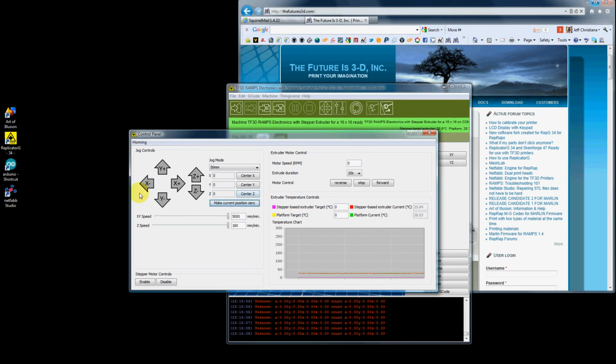These numbers mean nothing when you start printing. This is only a way of manually moving your bed and print head around. This is only for testing. It doesn't care when you print, it doesn't care what is in any of this. All of control panel doesn't mean anything. I know a lot of you out there ask me questions about, I went in here and set the X and Y coordinates to 0, I went and did this and centered. That does not make the program, my start.g code file automatically homes, automatically sets it where it needs to go. And then in SceneForge under multiply there is a center function, and that centers your print head when it starts to print.